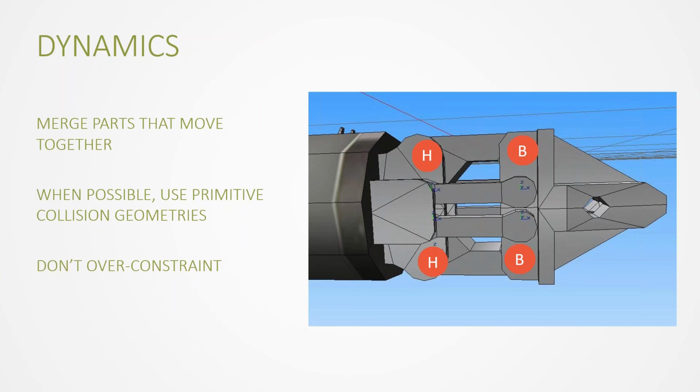But there's an even better way to do it, and that is by using an angular tree constraint, which means that the computer is going to be able to move it in torsion and sideways, and if you have energy or forces coming that way, they're going to have somewhere to go. There's going to be some give to each hinge on the side and in torsion, so that way the simulation is going to be a lot more stable. So I invite you to look at the technical notes in the Vortex documentation, to take a look at the whole explanation with the equation. And we have 21 constraints available in Vortex, so make sure you pick the right one to keep your simulation stable.